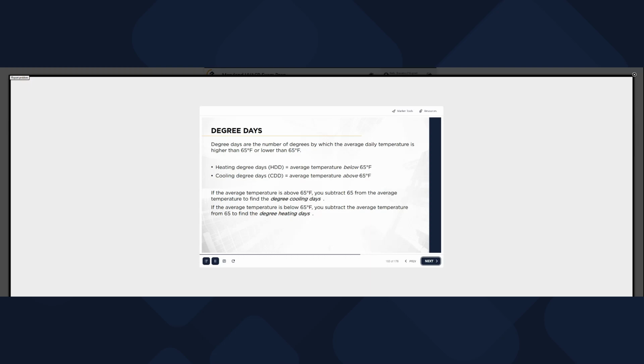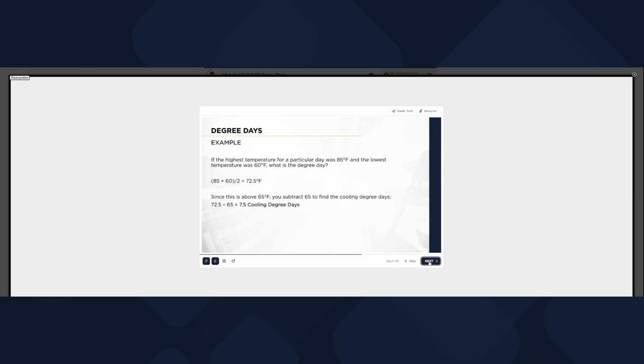If the average temperature is above 65, you subtract 65 from the average temperature to find the cooling degree days. If it is below 65, you subtract the average temperature from 65 to find the heating degree days. Let's work through a few example questions.